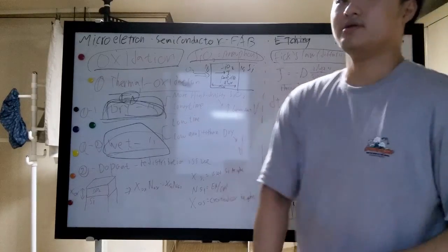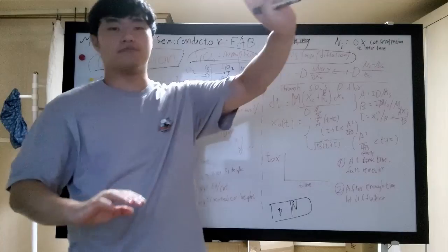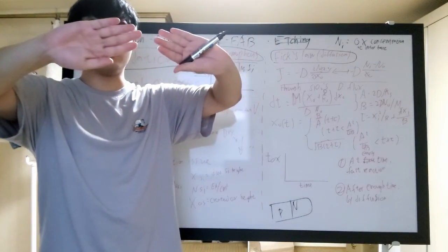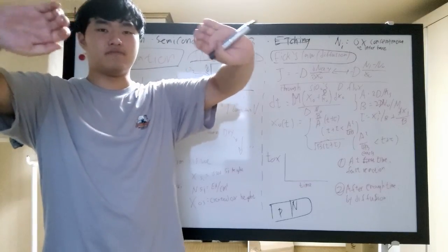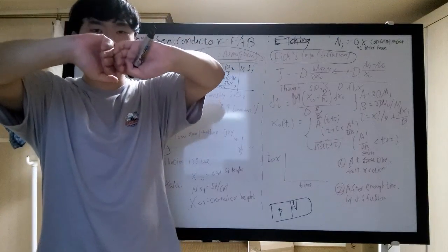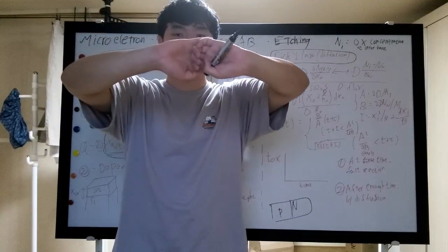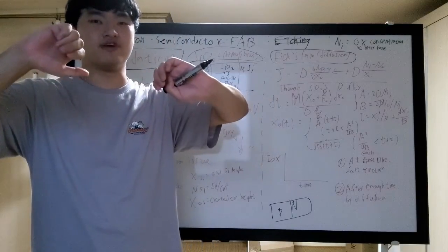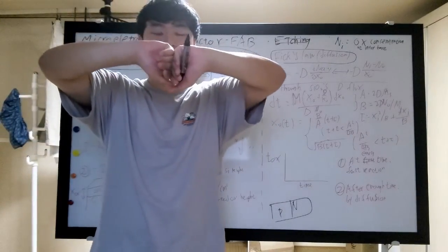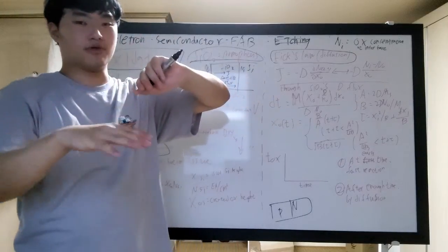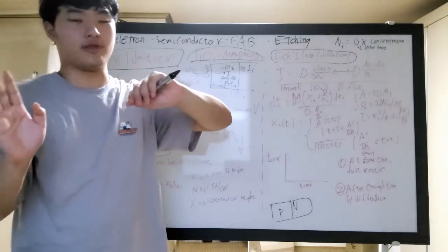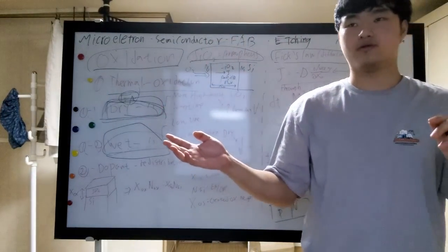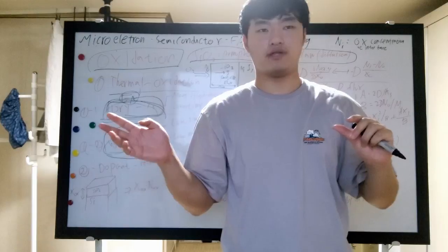See, my left hand will be the p-type silicon, doped, and my right hand will be the n-type silicon that has just been doped. If they meet at a junction by bonding, then the p-type has lots of holes, and the n-type silicon has lots of free electrons. With respect to the p-type silicon, the n-type doesn't have enough holes, and oppositely, the n-type also sees not enough electrons.